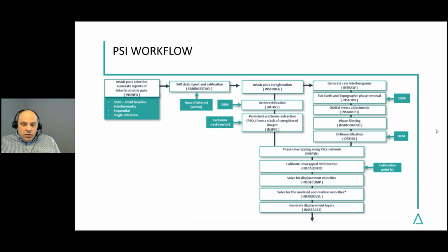So you have your time interval, and then you will compute the velocities for those time intervals. And you do some statistical fitting to have smoother velocities. And then once you have your velocities, the last piece is to compute the displacement. You have the choice between computing the cumulative displacement, or just the displacement for every layer. And what you get in output is a stack of data that you can convert to points and